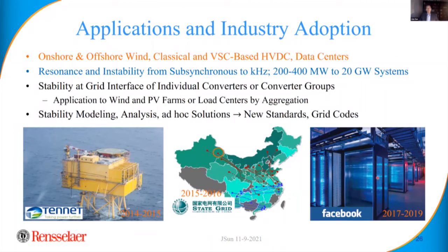In the last couple of years, I've been working on the load center. So interestingly, when we build these large load center data centers with hundreds of megawatts of loads, stability of that distribution system also becomes a real challenge. So there was resonance issues in data center power system. We also wrote a couple of papers. So these are more or less all in public domain.